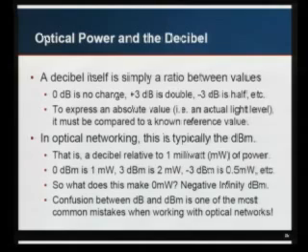And people have asked what's an actual no signal, and that's negative infinity dBm. There's been some cases where vendors, when you have power readings DOM built into your optics and you have 0 power, report 0 dBm, and that's actually a really strong signal. So the correct way to express no signal at all is negative infinity dBm.